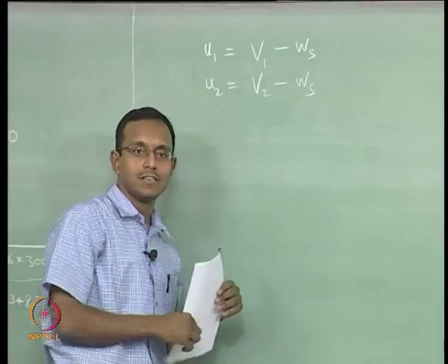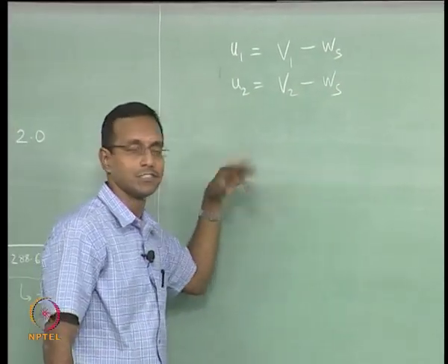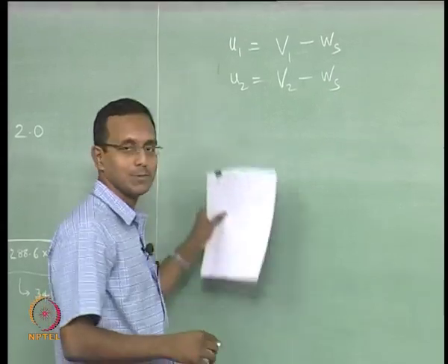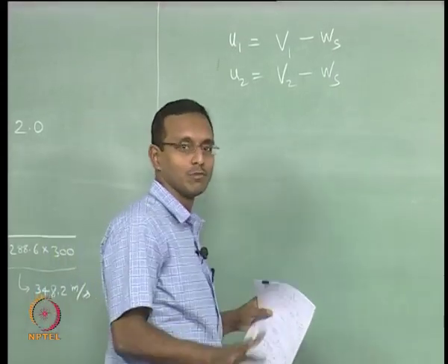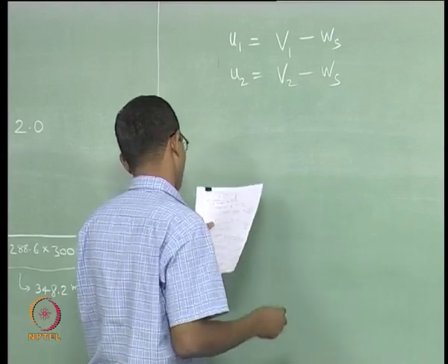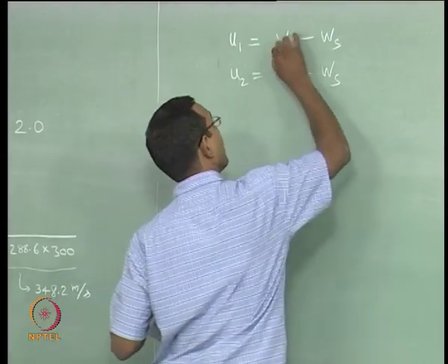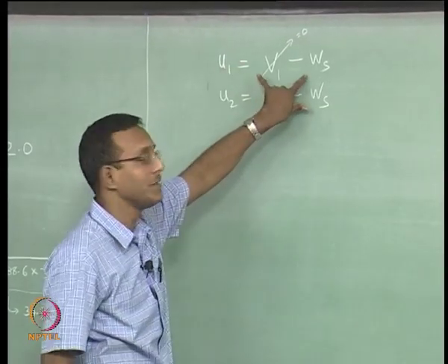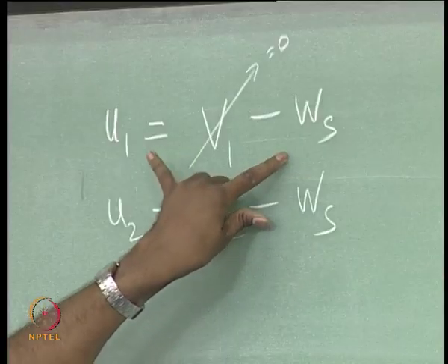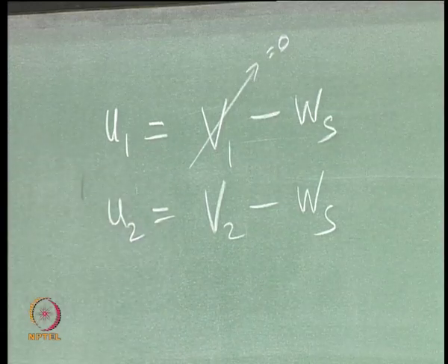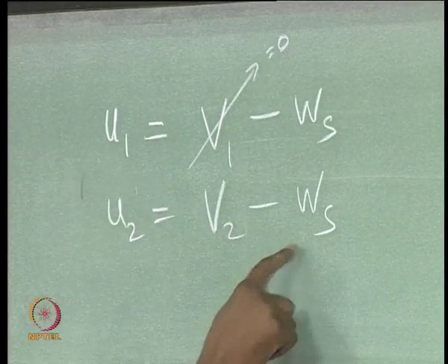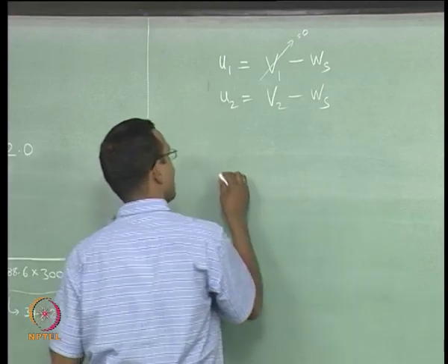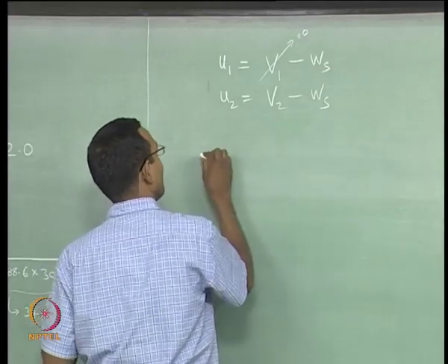This is the transformation between the two coordinate systems. These are the expressions which are always used in solving moving shock problems, very easy to solve this way, and we know in our case v1 equal to 0, and this information has already been used. We already found u1. Now all I have to do is substitute that in here, and then I am going to have a set of expressions to solve for.